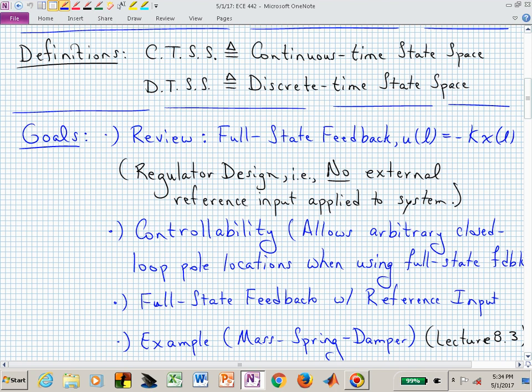So you can have K being short and wide, but depending on how many state variables you have, the width of that K matrix can start to collapse. And if your state vector, if you just have one state variable, then you in fact do have a scalar full state feedback gain matrix K, which is a matrix that's 1-by-1. But we're going to call that a regulator design when we don't have a formal way of injecting a reference input to track.